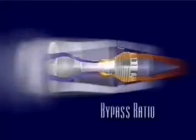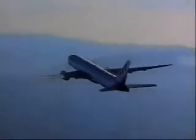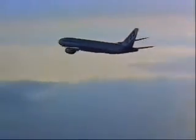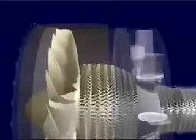Only 15% of the air flows into the interior core of the engine. The remaining 85% of the air is ducted along the outside of the core and is forced through an ever-narrowing space, the fan duct, picking up speed along the way. The ratio of this air bypassing the core to the air passing through the core is called the bypass ratio. Because of its huge volume, the bypassed air only needs to accelerate a small amount in order to develop an enormous amount of thrust. Meanwhile, the other 15% of the air has entered the first component in the engine's core,